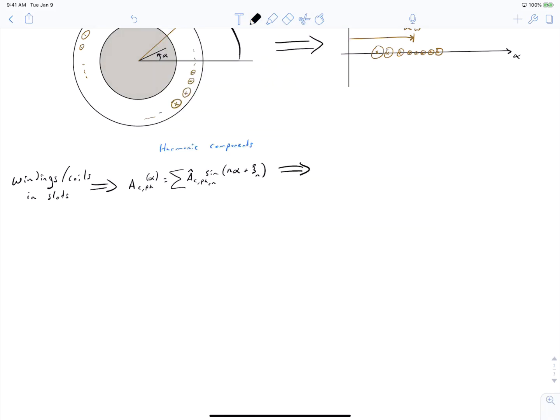And we can go from that to selecting a single frequency to work with, and then having three-phase distributed windings and exciting them with three-phase balanced sinusoidal currents. And from that we can make this observation that we end up with an equivalent rotating circumferential current density on the inner bore of our stator.